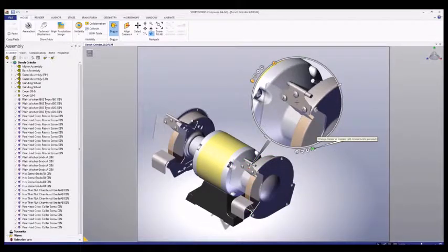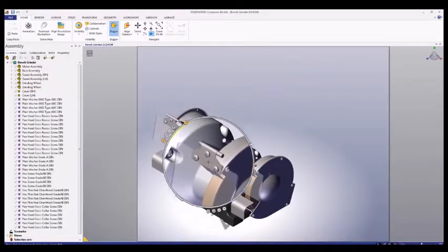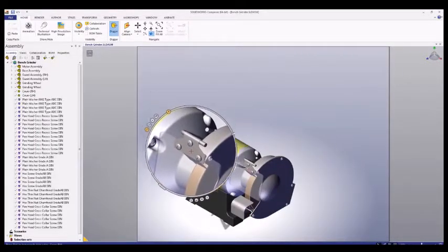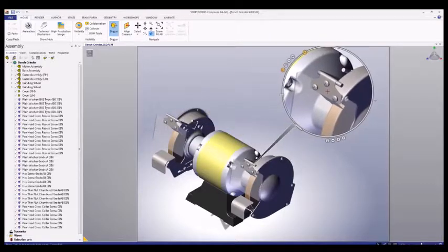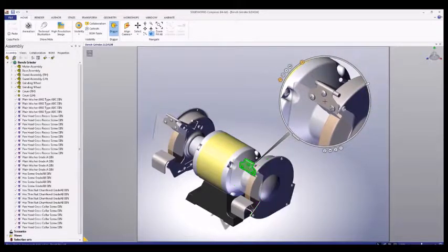Let's start with the Center of Interest tool. The center of interest is what governs what will be displayed in the Digger window. In this case, our center of interest is marked with a red dot on the shield assembly. By default, the Digger will not have a fixed center of interest. It will simply display whatever lies underneath it.